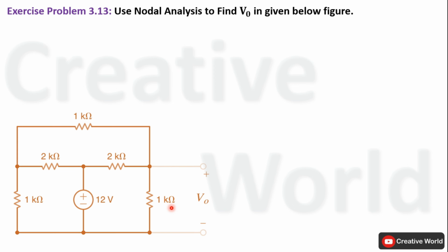We know that in order to apply nodal analysis on any network, we have to follow some steps. The first step includes finding out the maximum number of node voltage equations that can be retrieved from that network. Using this equation, we can find the value of that figure. In this equation, n represents the number of nodes that exist in the network. In our case, there are 4 nodes. So 4 minus 1 will be equal to 3.